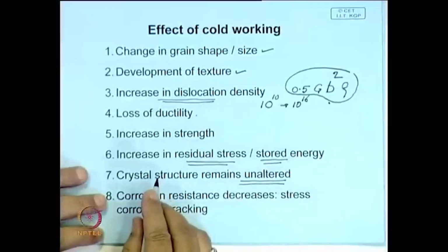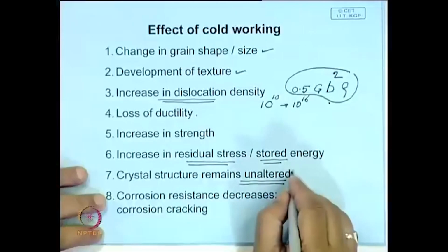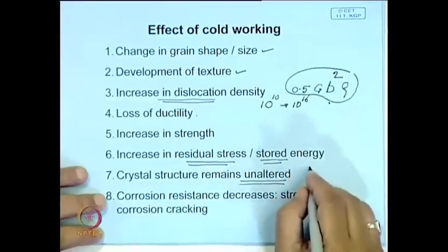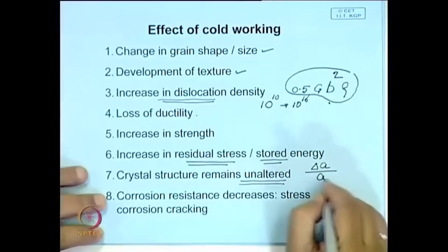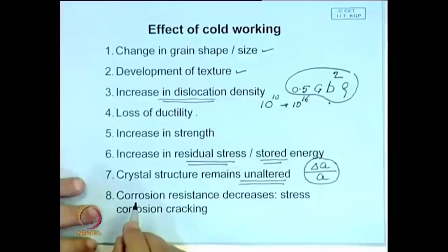Because of lattice residual stresses, the lattice parameter may change slightly, and the spread in lattice parameter measurement may be wider, but the crystal structure remains unaltered.